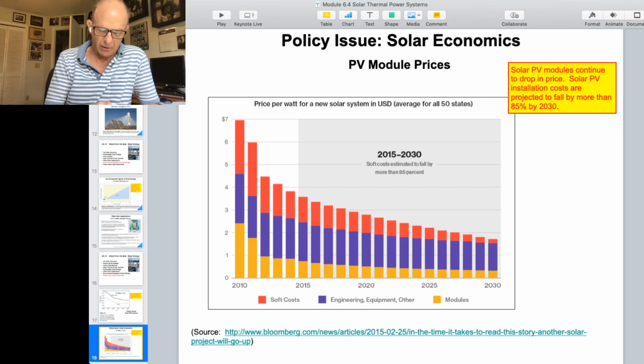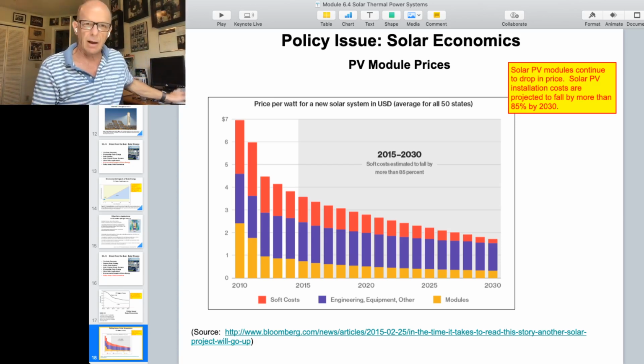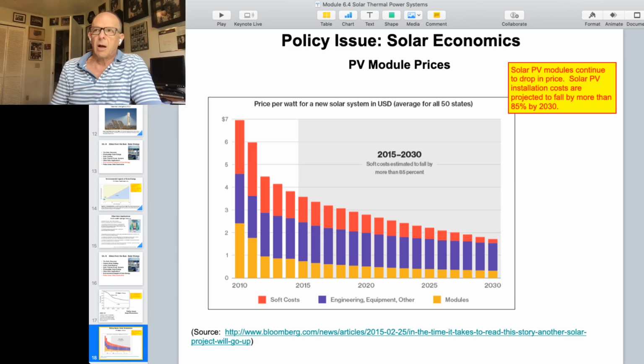So that's 26,000 kilowatt hours, and a kilowatt hour is about 13 cents. So that's about $3,000 of electricity that's been generated by that system. So the economics of solar photovoltaics are that banks typically provide a loan, and the cost of paying off that loan equals the cost of your electricity savings that you're no longer paying to the utility.